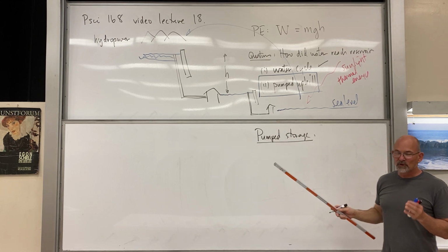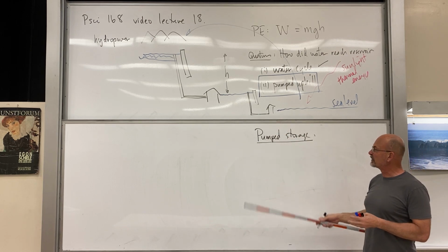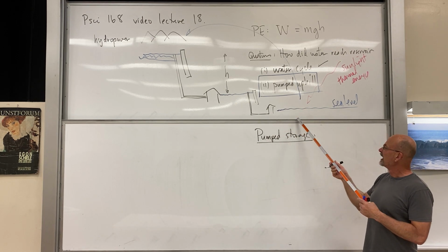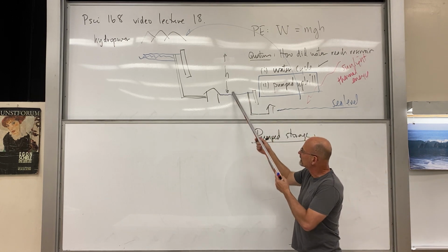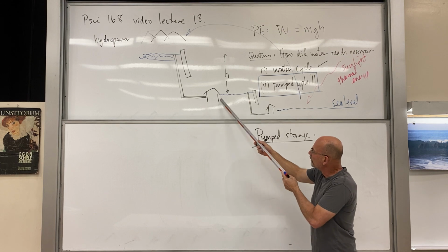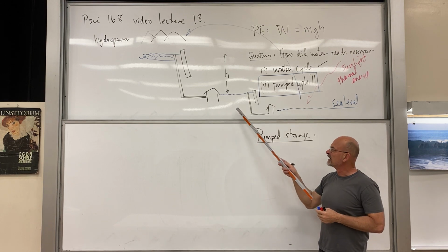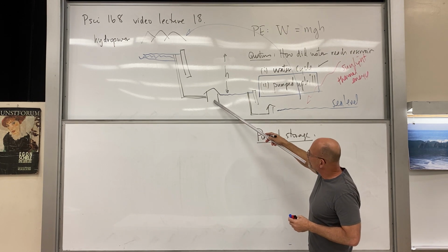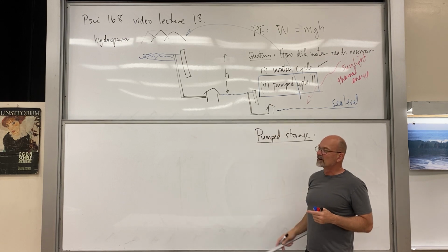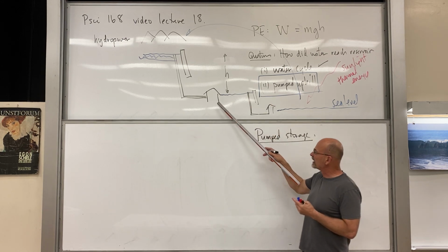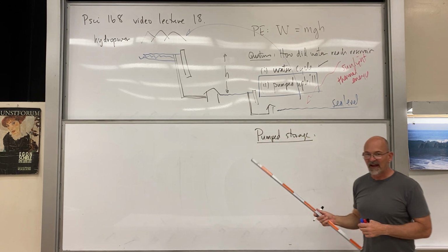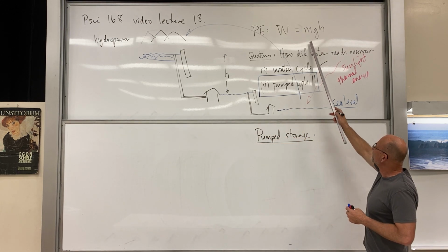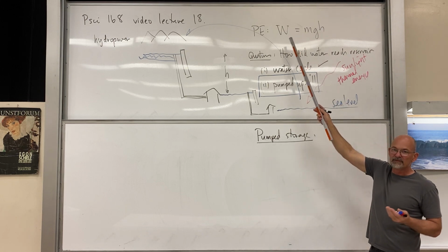So somebody's producing excess energy, maybe 100 miles away, and the operators of, say, this powerhouse right here will purchase that energy. They'll use it, they'll run their pumps, actually they'll run their turbines backwards, so to speak, and they will literally pump the water up the hill. And how much energy does it take? Well, this much plus whatever inefficiencies are there.